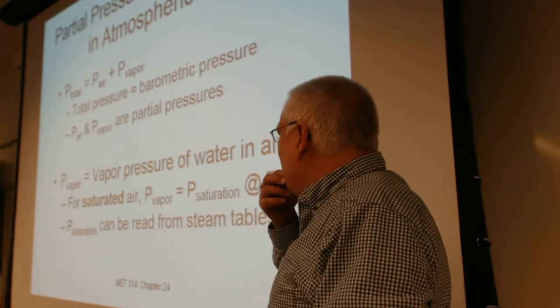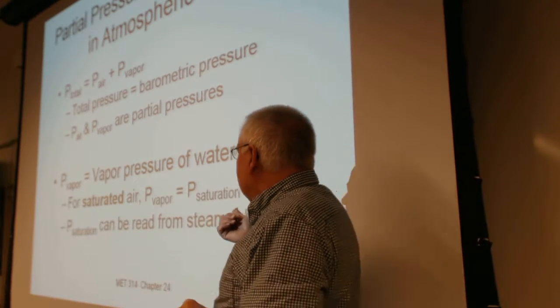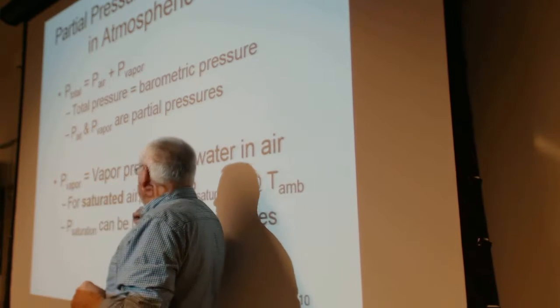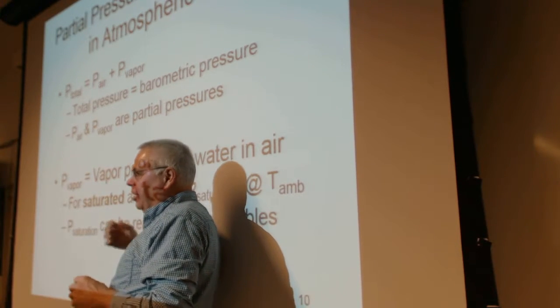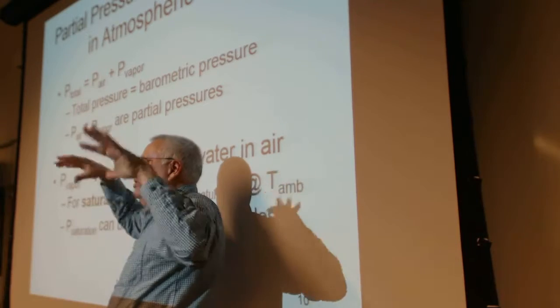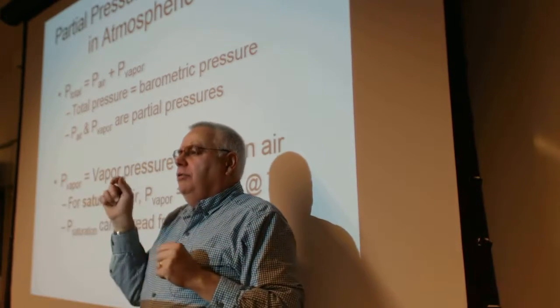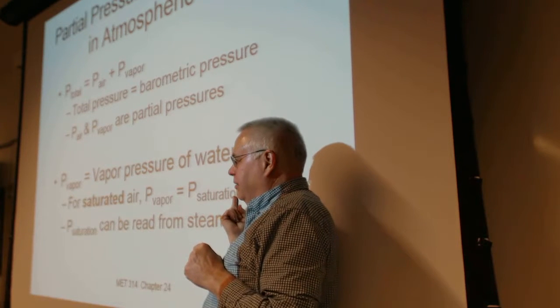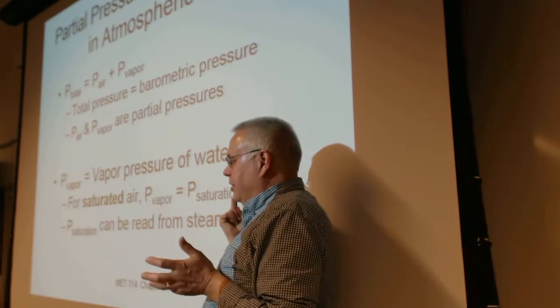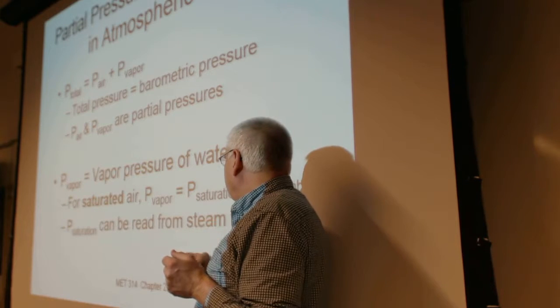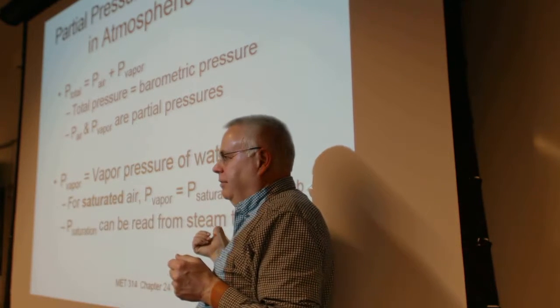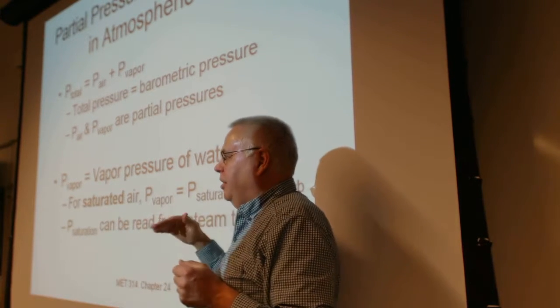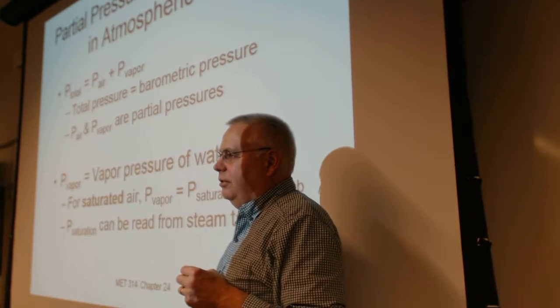So saturated air means that enough molecules of water have come into the air such that the partial pressure of the water vapor equals the saturation pressure from our saturation tables. And that's straight off the steam table. If the partial pressure gets that high, that's 100% relative humidity.